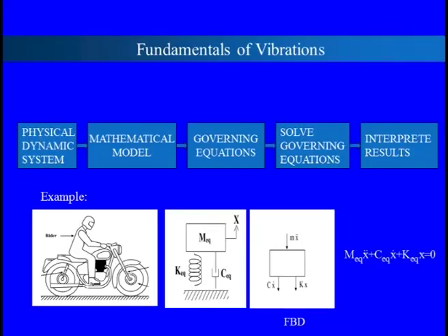And then we have the damper. The two struts are there, the front wheel and the rear wheel. So you see, this is the equivalent feature. And then when we map into the other part, we want to generate the third part, the equation generation, that is, what exactly the equation of motion is. We need to first put the force balance condition. On the mass, we have all three forces: the inertia force, restoring force, and damping force, as we can describe here. And once you have this, you have the equation of motion, as we discussed already: m x double dot plus c x dot plus k x equals 0.